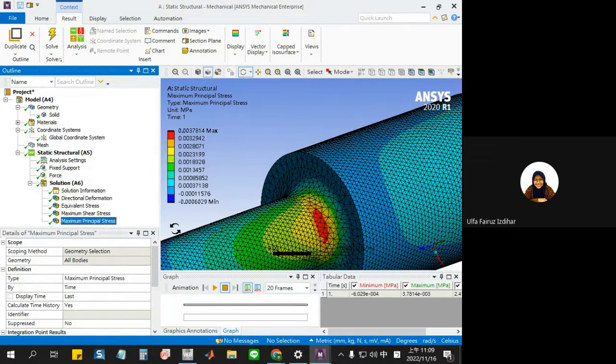So we know the maximum shear stress model tells us your largest shear needs to be smaller than your yield strength over your safety factor, and for shear it is divided by 2.